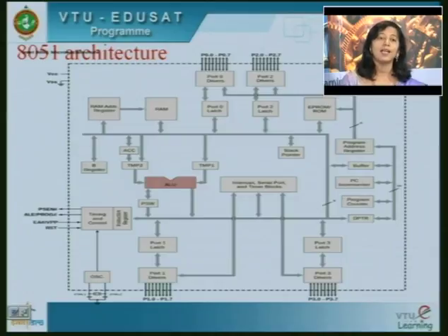The other operand can sometimes be there in the B register. Usually for multiply and divide instructions we need this register, but almost every operation, whether it is add, multiply, AND or XOR, whatever, one operand is always there in the A register or the accumulator.